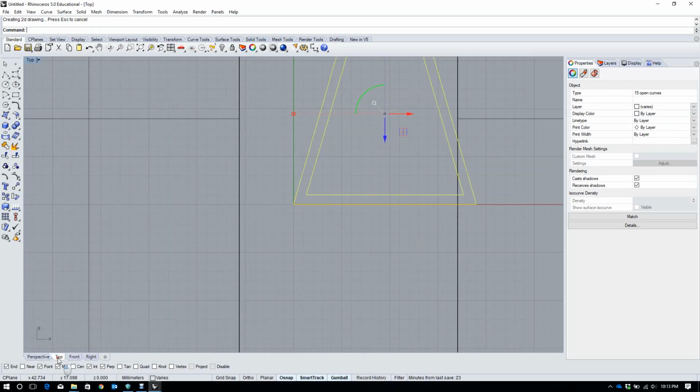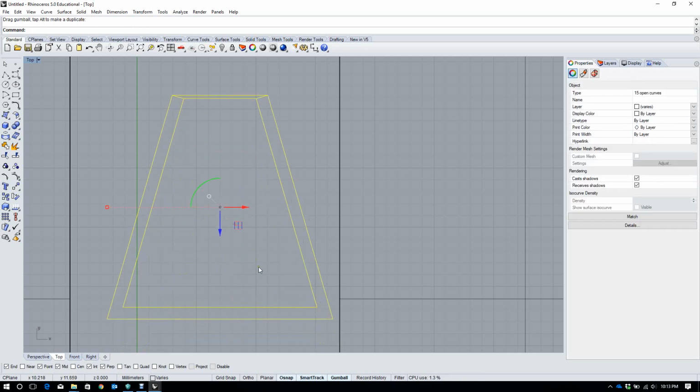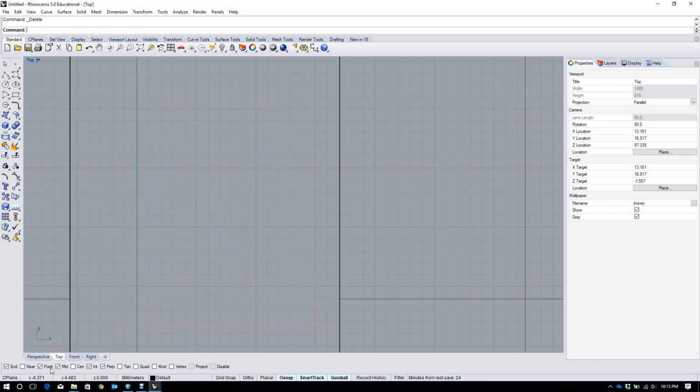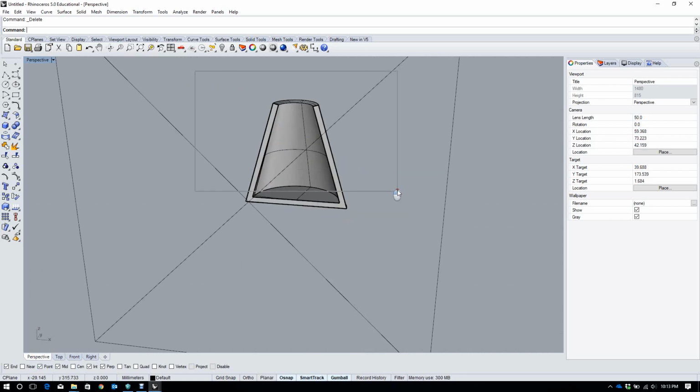Click OK, go to top view. Okay, yeah, so it does actually make 2D of your clip plane, or of your clip view. So that's good. That's one way to just cut a section: use the clip plane, select the object and make 2D.